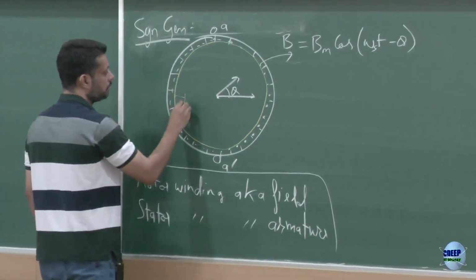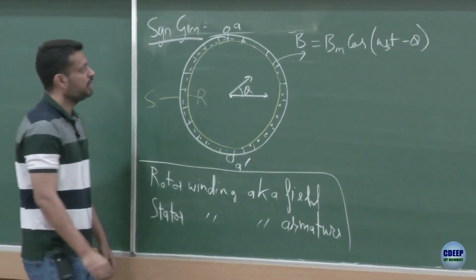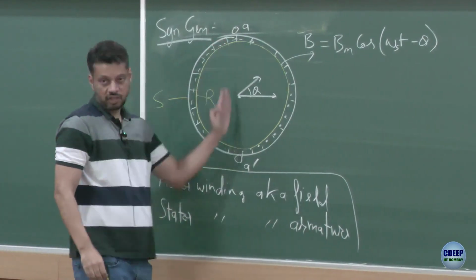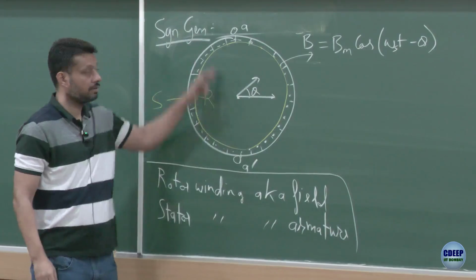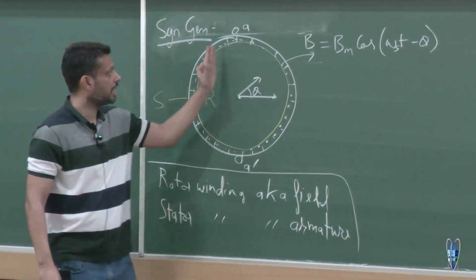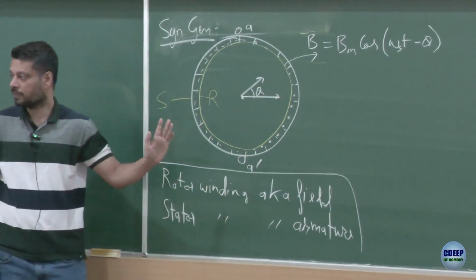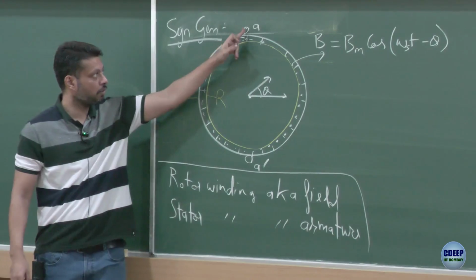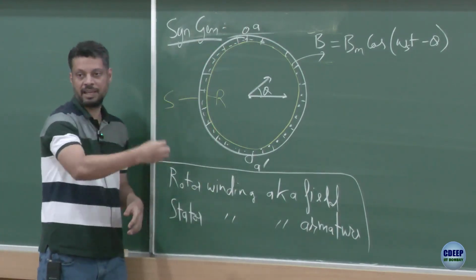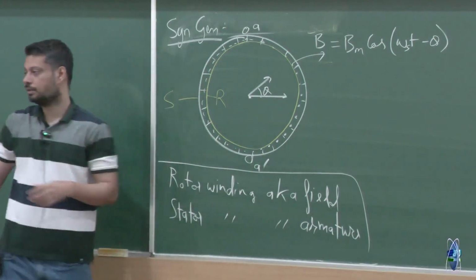So inside is the rotor, the outside is the stator, right. If I have to see how much flux is crossing this turn, which is like this, essentially what I want to know is how much flux is passing this vertical line. This is one turn: it goes inside, comes down, comes out again, goes up. This is one turn which is cutting the plane of the board.